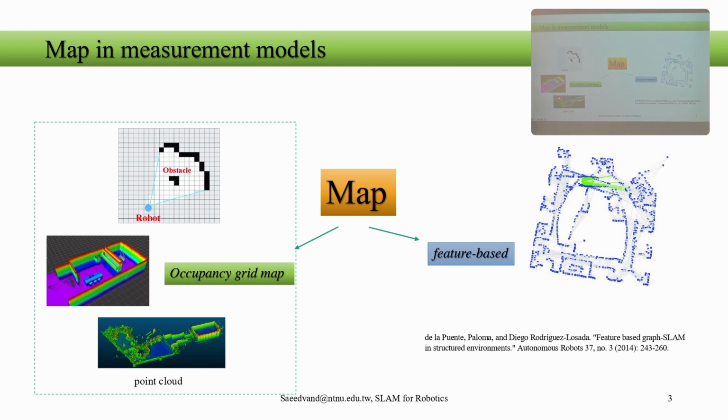So if we want to construct a 3D model of the occupancy grid mapping, at the beginning it may look a little complex, but in the simplest form we can just give a Z to the occupied location, since whatever is in the environment mostly has a standing point. It's not usually in the air. Because of that, we can simply use the 2D model and give it a Z to have the 3D model.